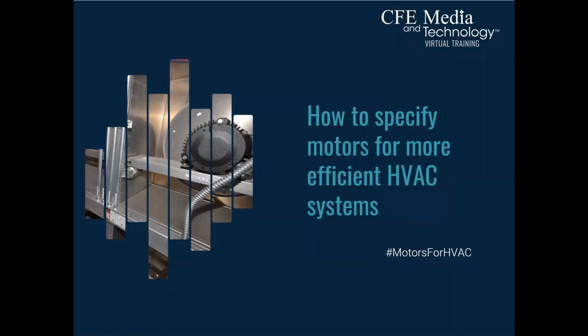After having designed hundreds of VF drives to replace standard motor starters, I found that it's more than just replacing the motor starter when you add a VF drive to a system. The first issue that you come up with is disruptive voltage wave harmonics, which carry out throughout the system and disrupt the operation of other electronic equipment throughout the facility.